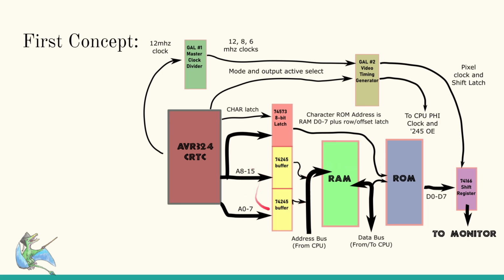Then we were going to put a buffer in front of each one of these. I went with a 245, even though it's a little bit more than we need, simply because I had them around and they have a convenient pin layout. The buffer simply takes what's on one side and shoves it through to the other.